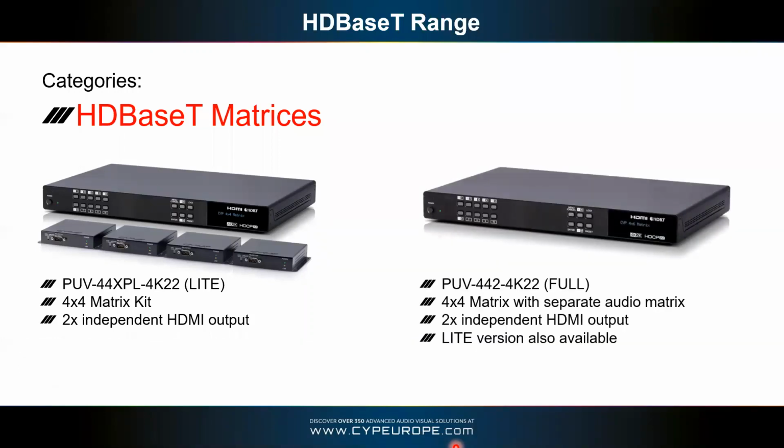Moving up from that, you've then got an HDBaseT full version. So being full, this one will then pass longer distances over the CAT cable. It has a slightly more advanced audio matrix as well. So this one, it's not just audio de-embedding. You can actually choose to route the audio separately. And again, because it's full HDBaseT, this model can then handle LAN serving. So if you need to get a LAN signal from the matrix to the endpoints, this will allow that because it's full HDBaseT. At the bottom there, sorry, I have just seen it says light version available.